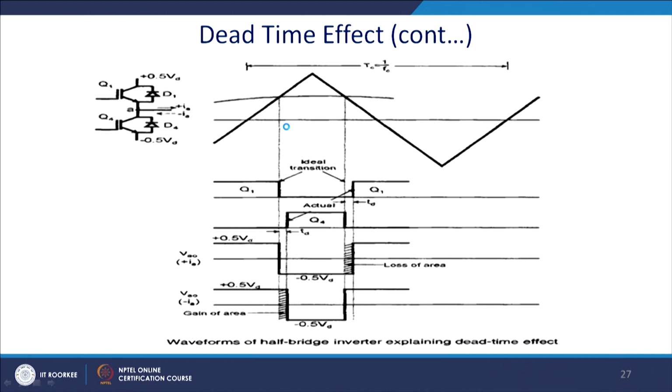See, this is sine triangle PWM, and this is the ideal transition, this point and this point. But if you give a delay here, ultimately it will start conducting with a little time difference of Td. It depends on whether the load current is positive. When this transition occurs, it will be lossy.